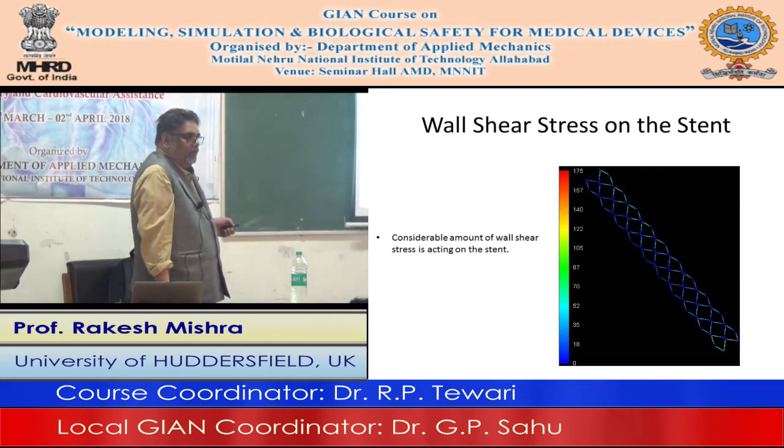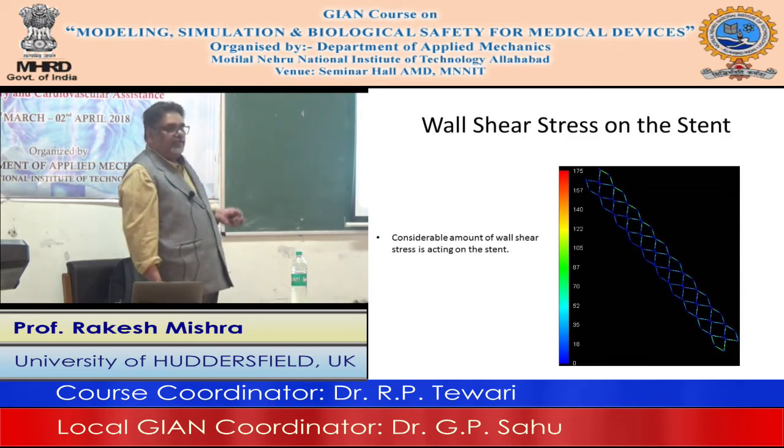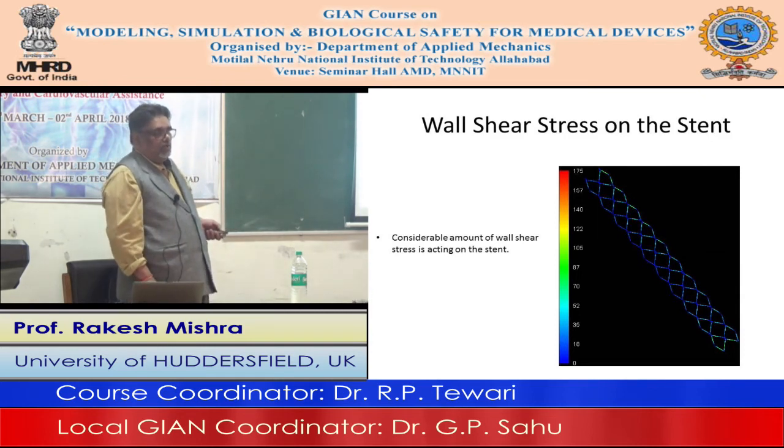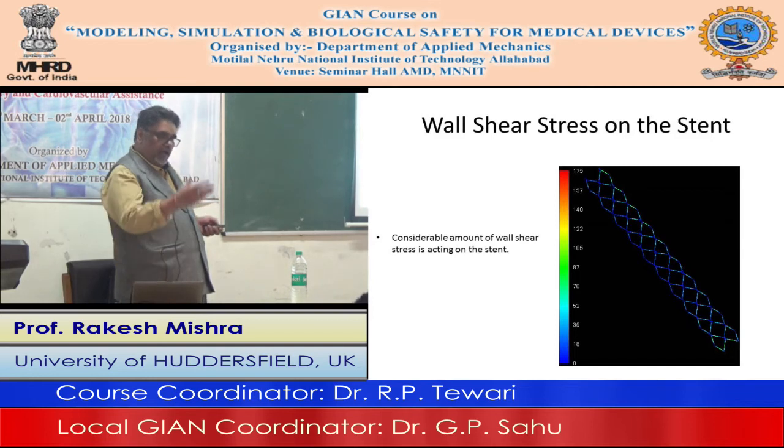Okay. Where these are very, very high, that is where the wall shear stress can start affecting the blood flow or the blood composition, and thrombosis and things like that can start taking place. So it gives us an idea of which are the areas where things can go a bit wrong in this particular flow situation. Okay. And then the next stage comes to modify the geometry.